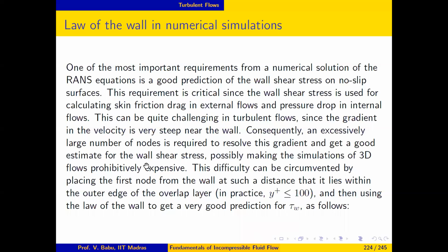So if you want to get a good estimate for the wall shear stress, the number of nodes required may be so high that it is not possible to carry out simulations of three-dimensional flows. And most flows of engineering interest are three-dimensional and turbulent. So this is actually a vexing problem which we need to address.